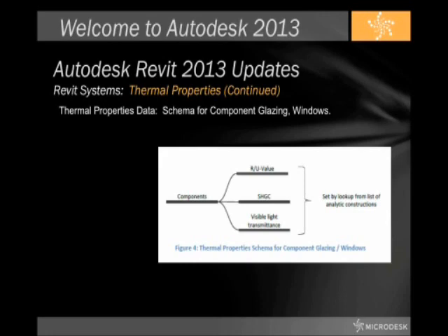So when we're choosing to export that information from spaces, by default the analysis properties are generated from the information that you're seeing inside the model elements, and the properties of the analytic construction are used when override is selected for missing model information. Any upgraded files will also have an override, which can be checked to provide consistent behavior with 2012. And if no thermal data is assigned to the various model objects, the thermal data from analytical constructions is going to be used.